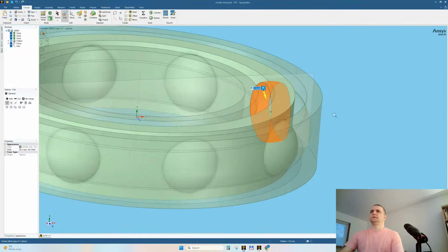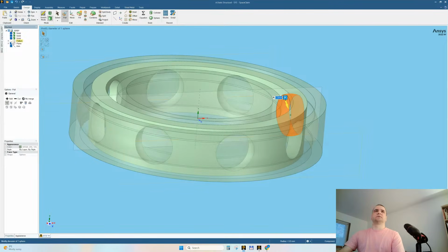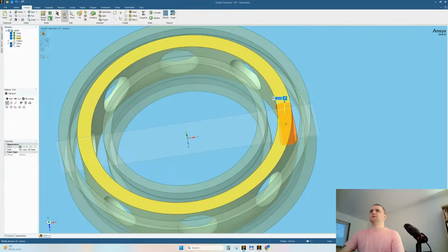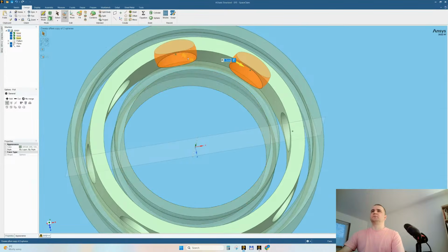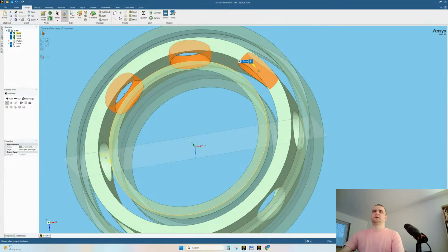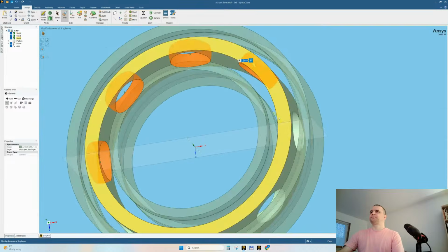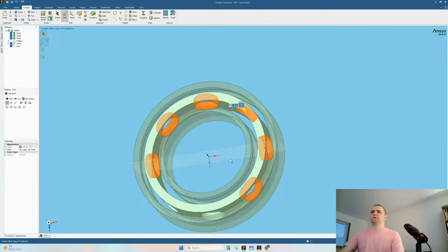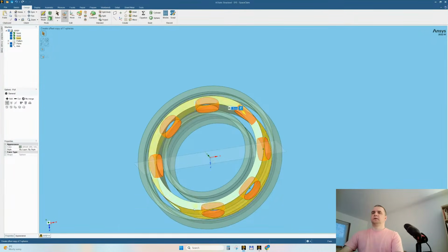All right. So the easiest way, in order not to think too much, is to click each of these cutouts with Control pressed. This is the easiest way. And instead of 3.5, let's make the radius 3.55.